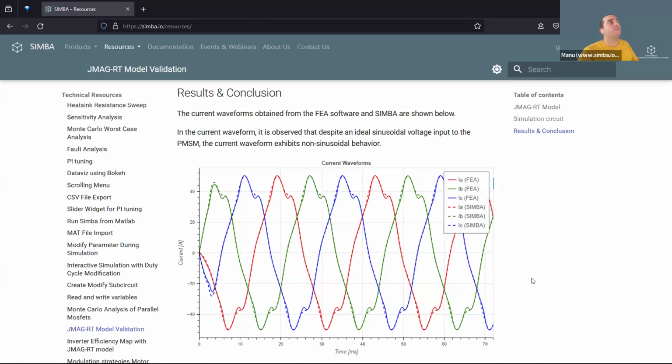So I will answer this one. Yeah, we can get relatively good detail. I would say it is a little bit similar to SPICE, it will just be faster than SPICE. That means we have detailed semiconductor models, we can have filters like common mode chokes, and we can simulate PCB parasitics. For the EMI, EMC standards, we don't have those directly in the user interface, but we have some examples in Python where we run a Python script and export the waveforms through FFTs, and we compare with the EMI standard.